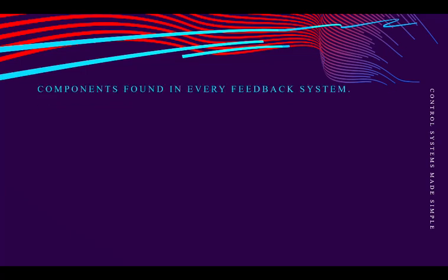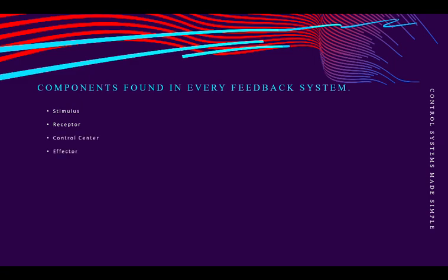So basically, both systems differ in terms of accuracy, where the closed loop is fitted with a feedback system while the open loop isn't. This feedback system regulates the input if the current output doesn't meet the desired output that is needed for the device or process, in turn making those devices or processes more accurate.